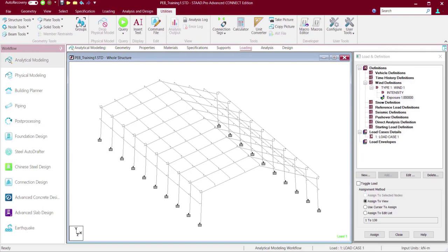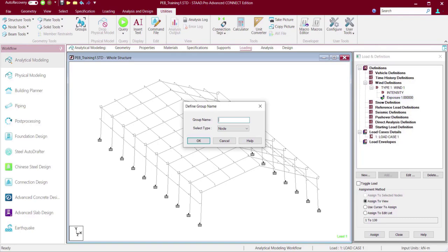For example, if you want to apply the floor load on some panel, then group definition is very much essential. If you want to select a few of the members, for example, a set of trusses, you have tagged them as a group. Then with a single selection by the group name, you can get all of them highlighted. So we have different advantages if you group them, for a hassle-free and much more convenient workflow.